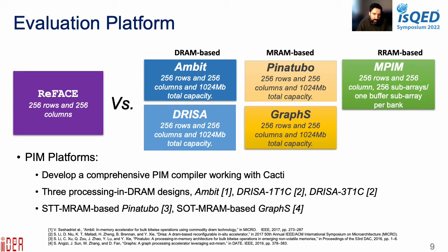A 256 by 256 memory subarray for each memory technology with peripheral circuit is utilized. And for architectural level, we developed a PIM support evaluation tool on top of the MVCM to model the timing, energy, and area of various PIM technologies. A behavioral level simulator is developed in MATLAB, calculating the latency and energy that each platform spend on different tasks.